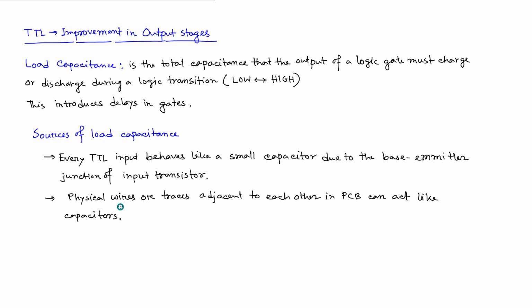And also sometimes whenever you have this circuit, these are printed on PCBs, adjacent wires, very close wires together, traces together, can introduce capacitance, because they are also a similar type of thing. Two conductors separated with some distance, there can be some insulating material or there can be just air. So still they can act like capacitance, and they can behave how capacitors generally behave.